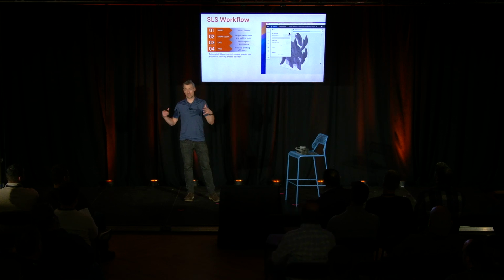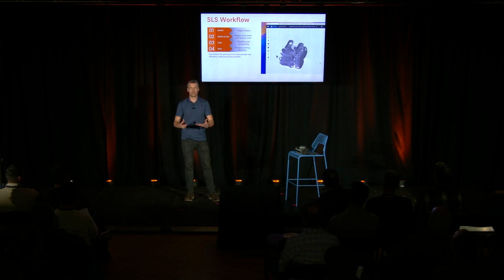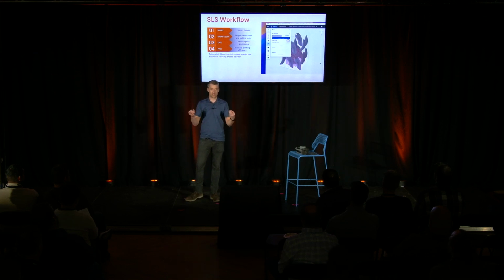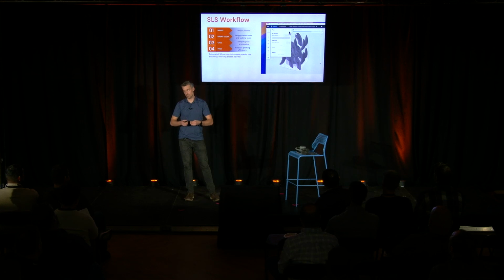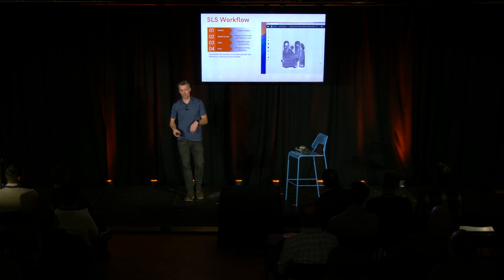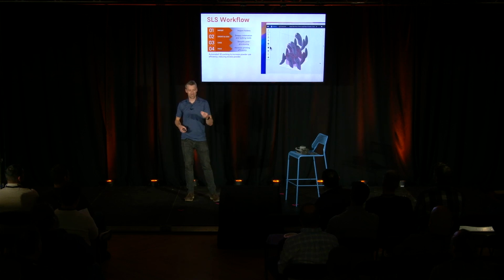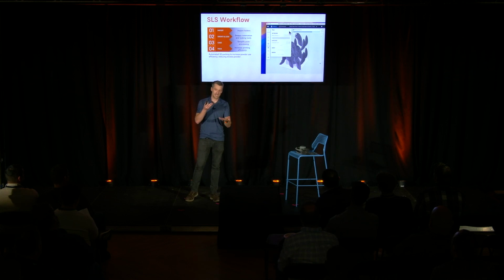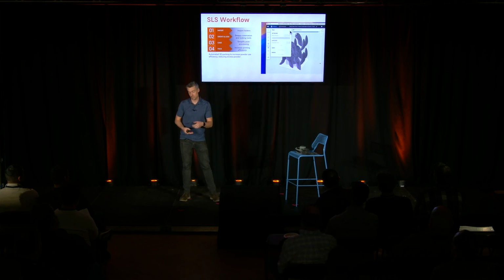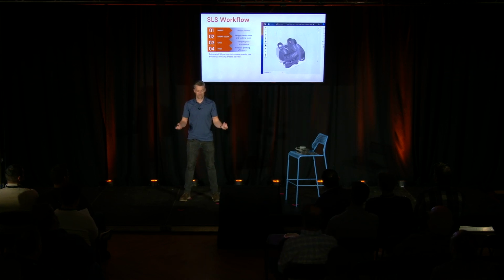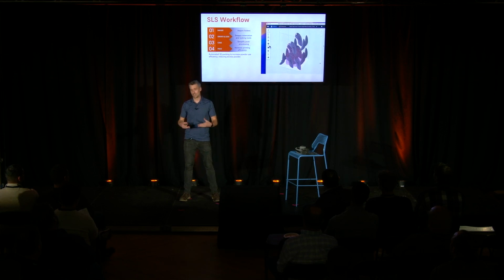So packing makes it so that you can take all of your parts, get them as tight as possible, and increase your packing density, which when you think about packing density, you always want to compare that with your refresh rate to understand how much excess powder you're dealing with. This can all be found in the print report, which is a tool. If you have questions about that, you can grab me after and we can talk about it. But the excess powder is the thing you're trying to avoid. So you always want to try to bring your packing density as high as possible to compare it to the refresh rate you're using. So using the packing algorithm, you'll be able to do just that without doing any extra work of manually packing yourself.